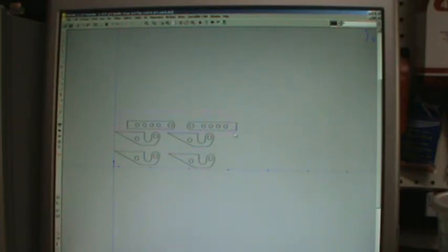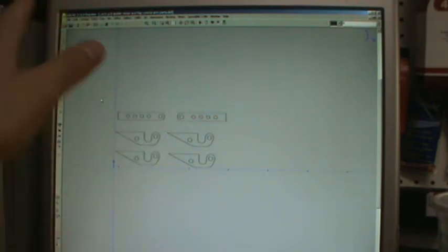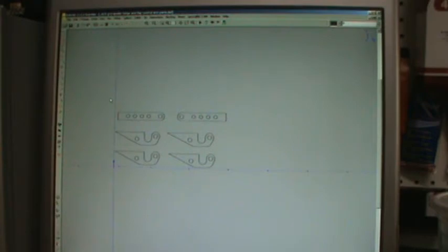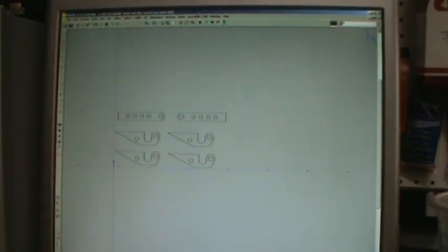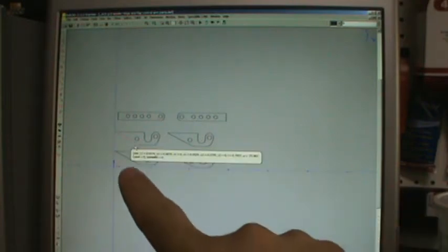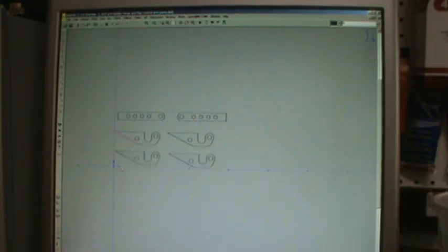And then these 2 parts here, same thing. I'm just going to highlight both boxes, change, translate, drag. I'm just going to raise them up a bit, hit the escape button, and then click on there so it deselects everything. Alright, so now we've got basically the parts we want where we want them. And we got them in the upper right hand corner of the 0x 0y. That way when we zero our router or whatever, it'll cut this direction into the center of our cutting area.